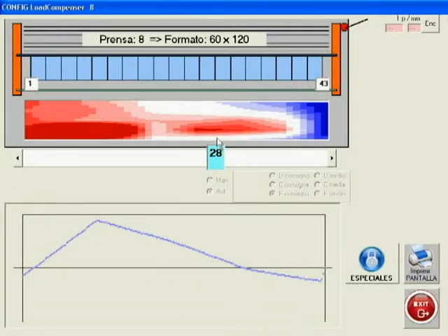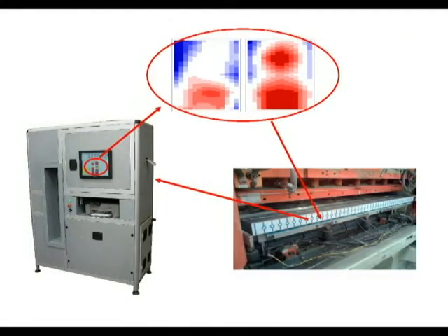In this example, we can observe the graph of each actuator with respect to the neutral correction line. During the retreat of the truck, each actuator will move according to its graph, adding more or less load of clay in the area requiring it, and even removing some of the material in the remaining areas. The combination of the two results in the total elimination of dimensional and surface defects, which to date were very difficult or impossible to correct.